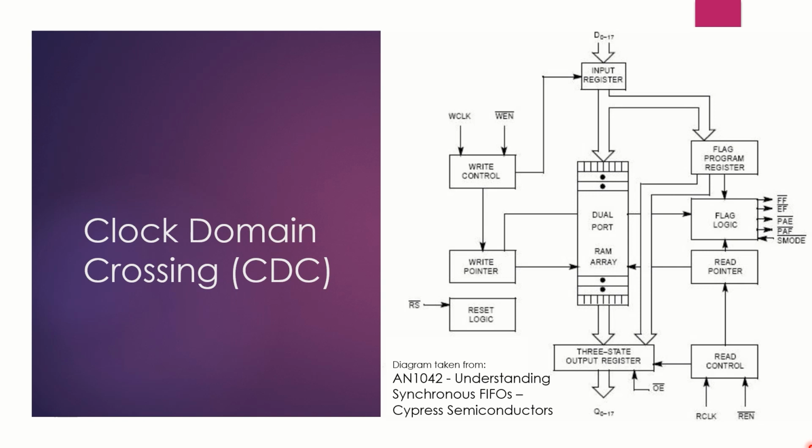The memory array is built from dual port memory cells. These cells allow simultaneous access between the write port and the read port. This simultaneous access gives the FIFO its inherent synchronization property. There are no timing or phase restrictions between the accesses of the two ports. This means that while one port writes to the memory at one rate, the other port can read at another rate, totally independent of one another, which makes the CDC system very fast.